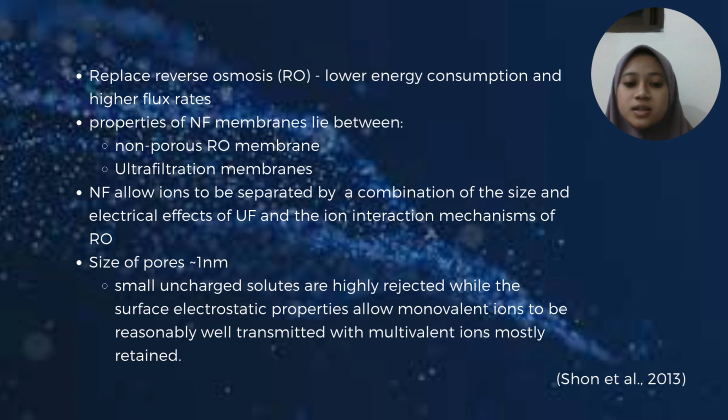The size of the pores of nanofiltration membranes is approximately 1 nanometer, and small uncharged solutes are highly rejected, while the surface electrostatic properties allow monovalent ions to be reasonably well transmitted with multivalent ions mostly retained.